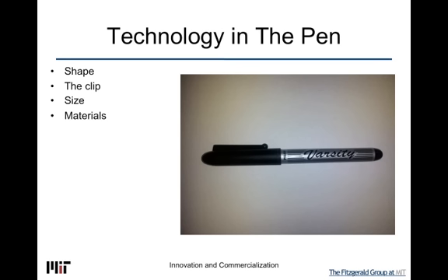And it's clear that if you're going to have a disposable pen, that probably injection molding plastics is probably a low-cost way to go. And indeed, this pen here is entirely made, except for some very small pieces, entirely made from plastic. So materials choices, anything from, at the high end, you could have very expensive metallic parts included in the pen.